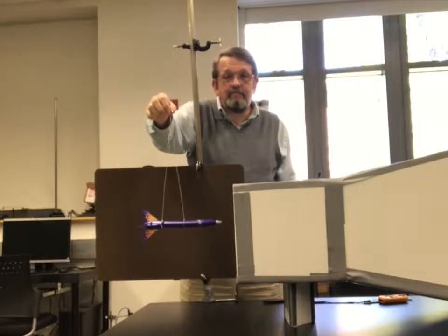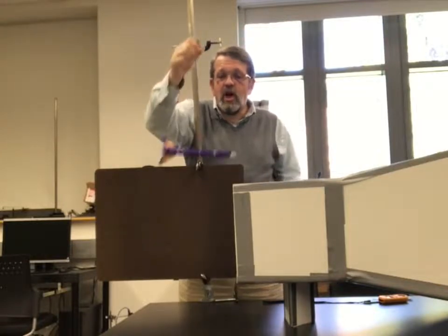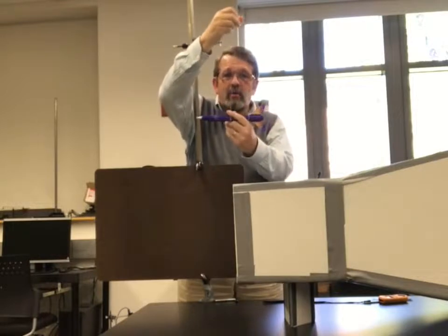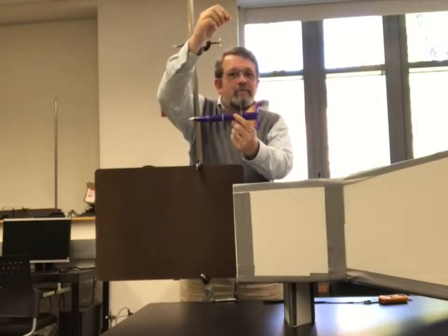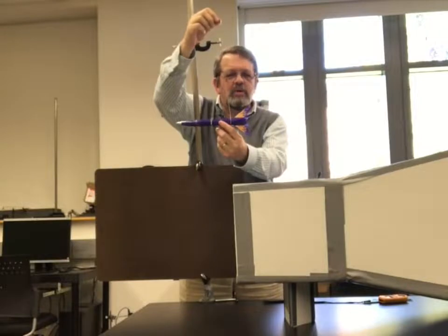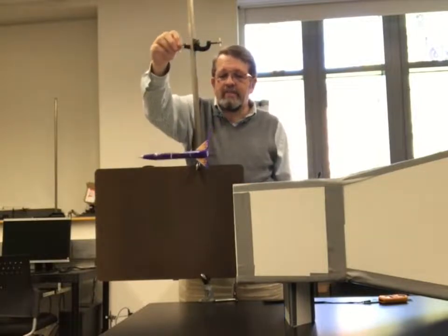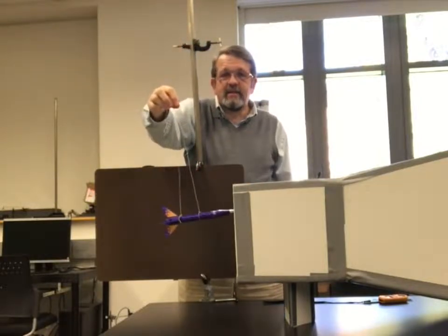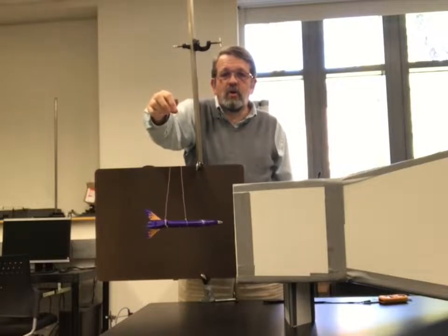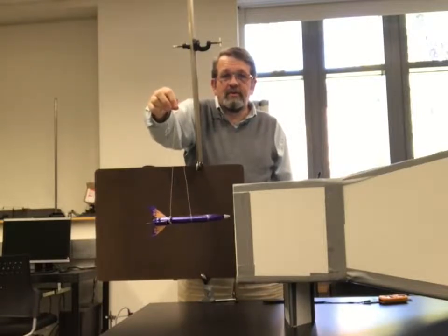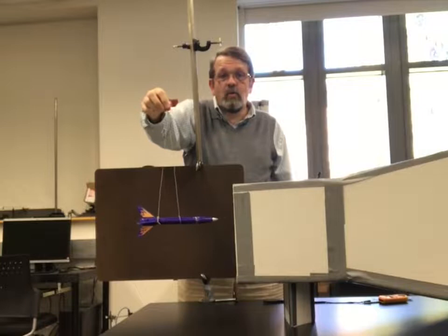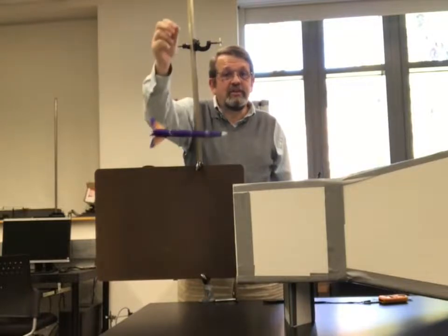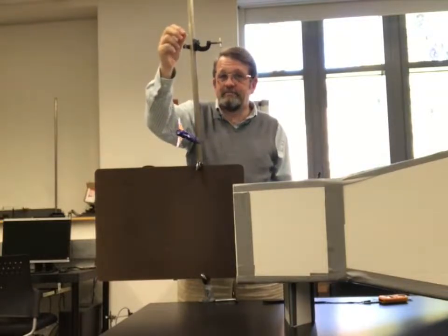It's aerodynamically stable in this direction. Of course, if the rocket were flying backwards, then the center of pressure would be in front of the center of mass. I wonder what would happen then? Well, what happened is the rocket would turn around, so it would go nose into the airflow from the wind tunnel. This rocket design is stable.